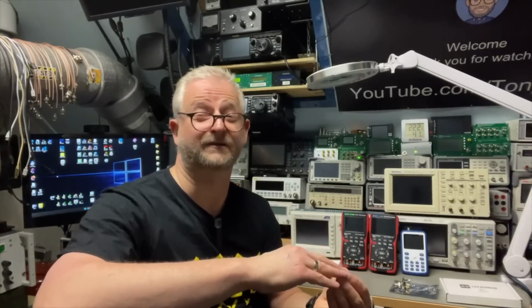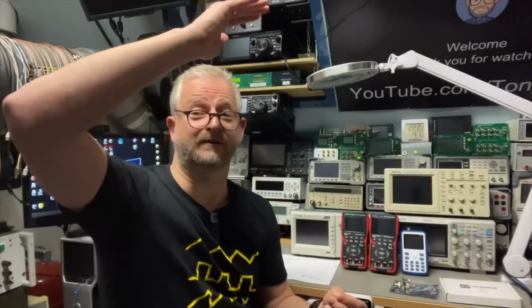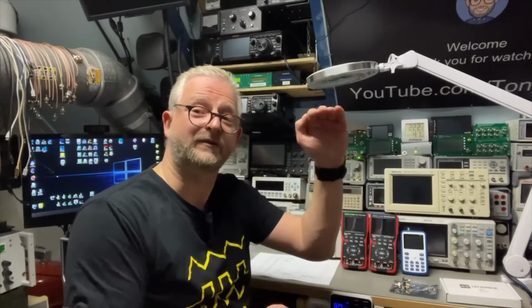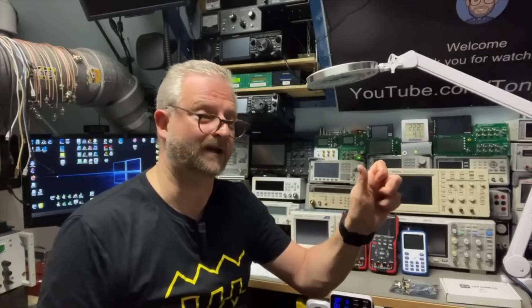That is another limit. And of course the slew from 0 to 1 volt goes a lot faster than 0 to 100 volts. So you need to keep your voltage down doing this test, and that is why you also have your 1x/10x switch on your probe. You do not need to go to these super high voltages, but keep it low, because that will go a lot faster.